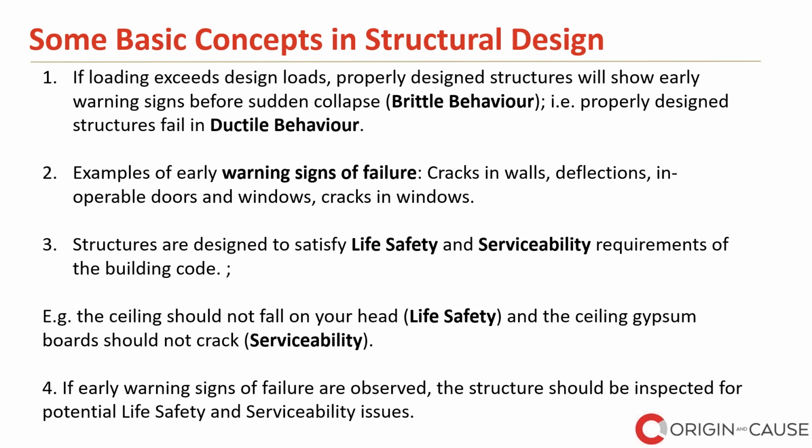A sudden collapse, we call it a brittle behavior, which is not favorable. So a properly designed structure will fail in ductile behavior. Examples of early warning signs are cracks in the walls or ceilings, or inoperable doors, like if they are stuck in their framing. These are early warning signs that you need to pay attention to.